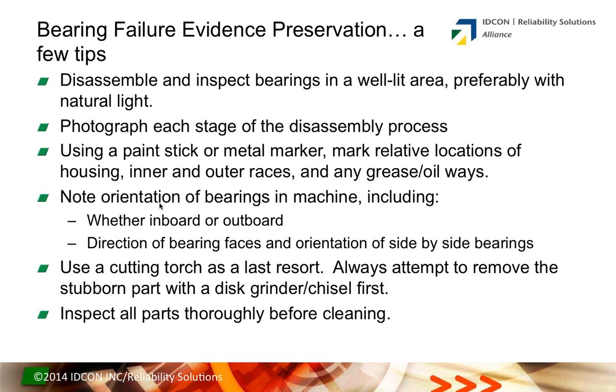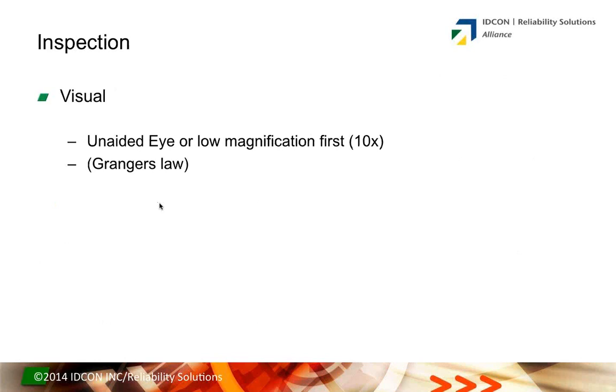Another thing that often happens is people want to clean parts, and particularly with bearings, you need to do your inspection before they're cleaned, because the dirt and the grease and everything else may provide vital evidence as to why that bearing failed. So we need to have that information.